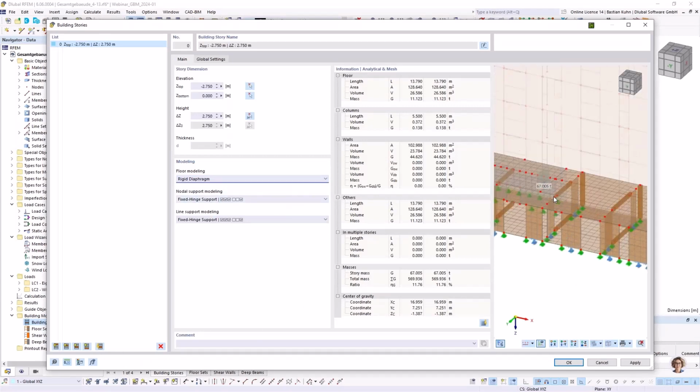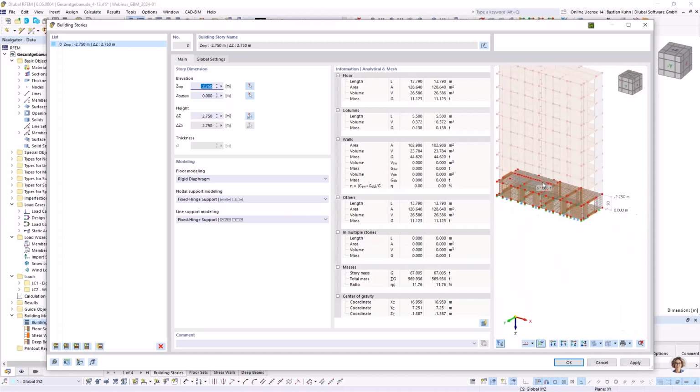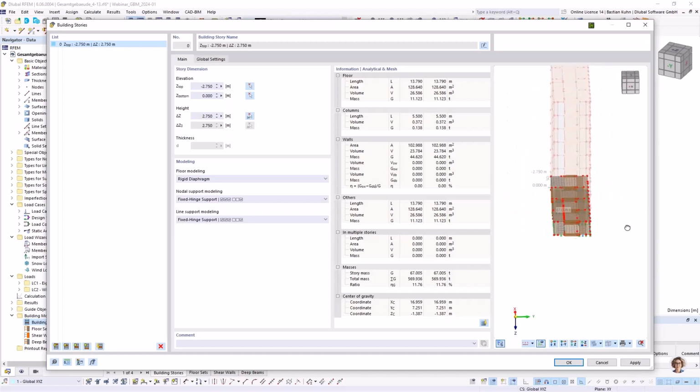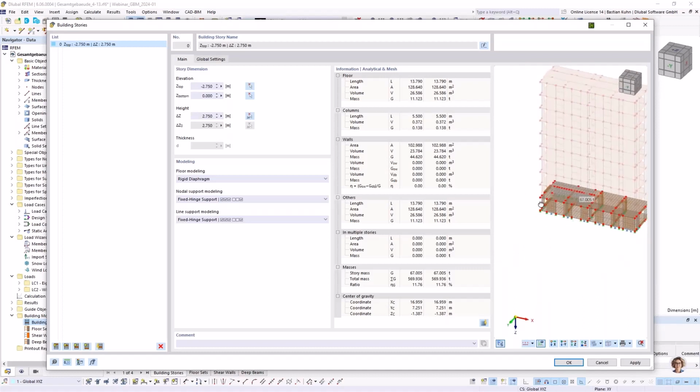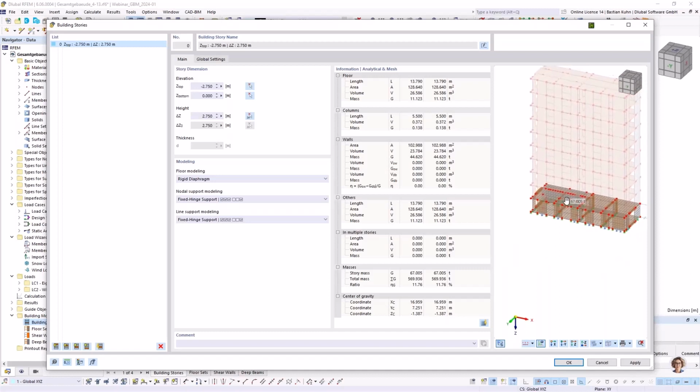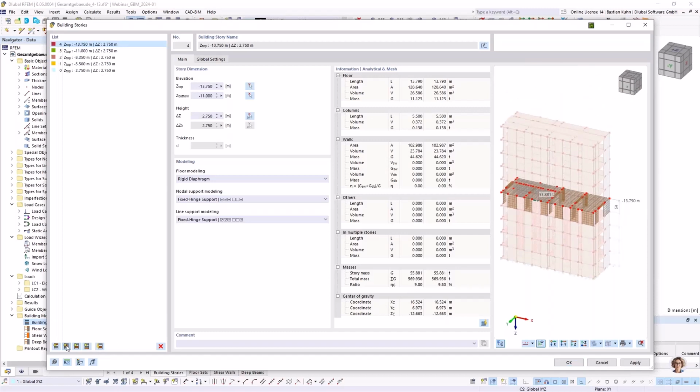Yeah, so the first story is already there. You see the software knows it is located the first story from the origin 0 to minus 2.75. I can always choose any level elevation that I want. I get a mass. I get also a mass center, obviously, where I'm having the concrete kernel. I have more mass, and that's why the mass center point is moved a little bit to the left side here, and afterwards it will also calculate us a stiffness center of the complete structure. So okay, I will do this now for all the other stories in here. So we have 9 stories in total in here, from story 4 to story 13. Here the top elevation, yeah.